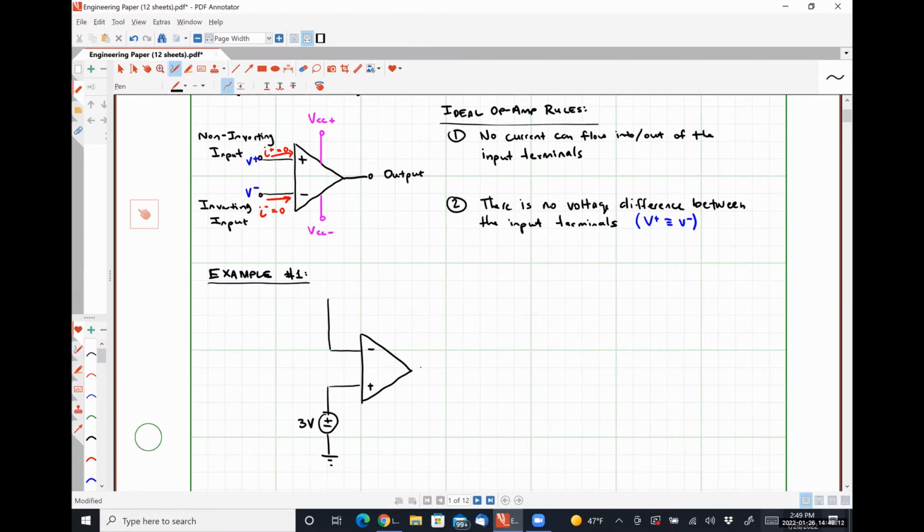And then I'm going to apply what's called a feedback resistor here, and let's make this guy 4 kilo ohms. Typically speaking, you'll see op-amp circuits are biased by kilo ohm size resistors for a very specific reason that is not remotely important to what's going on in this class.